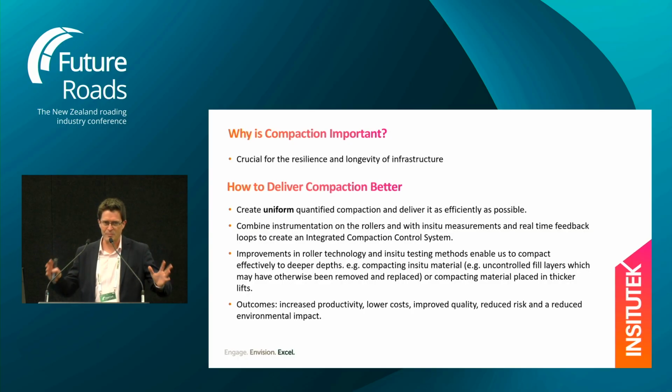All right, so compaction. How do we typically assess compaction currently? Talk to me. How do we do it? Probably through nuclear testing. Nuclear density testing, yep, that's one of the methods. Clegs, yes. Anything else? Any others come to mind? NDMs, yes. Scala, yeah. Those are typically the methods that we're going to be utilizing.